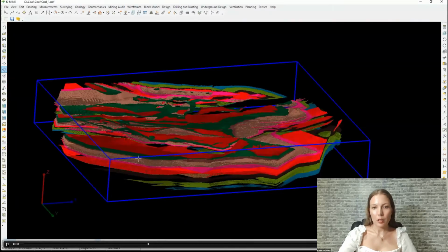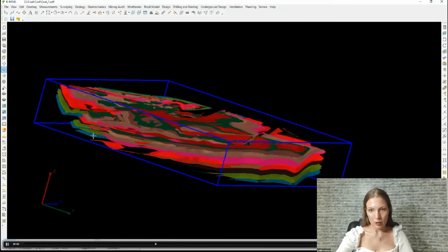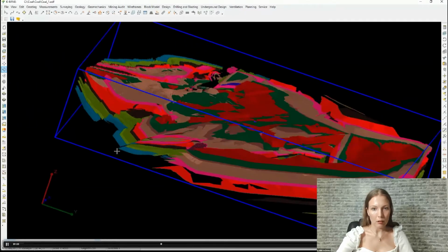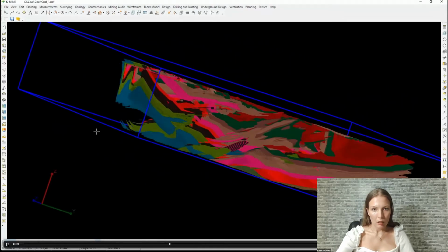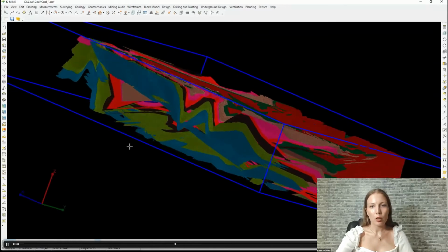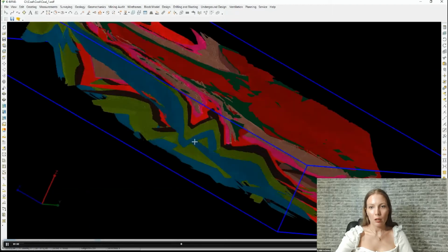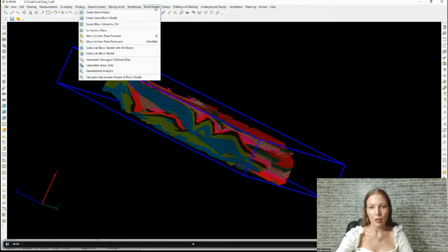And in K-Mine, a user can add physical and mechanical properties of rocks into the database for using the block model to calculate rock mass stability. And basically, rock mass stability in pit walls and section benches depends on lithological composition, also degree of fracturing, rock jointing, water bearing, and rock slope angles.